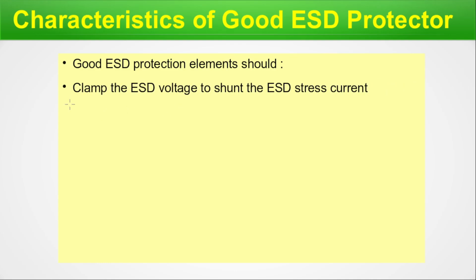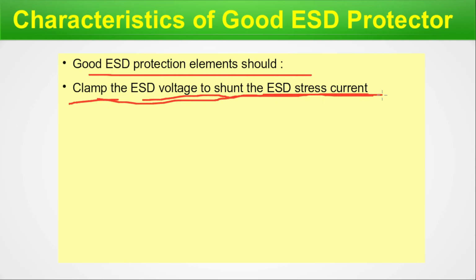Characteristics of a good ESD protector. In this slide we will talk about what criteria a good ESD protector should have. That means whatever we are incorporating inside the IC, these are the characteristics that the protection element should bear. A good ESD protection element should clamp the ESD voltage to shunt the ESD stress current.